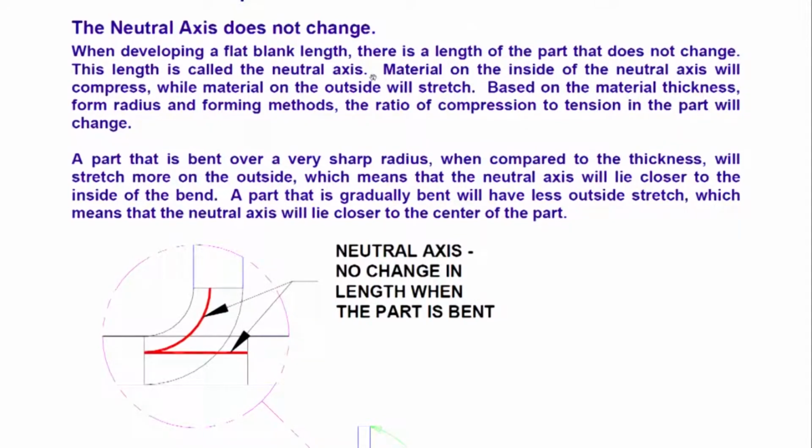You would have seen it when you bend anything in your hand, typically a small flexible material like play dough. When you bend it, you will notice that the inside gets compressed and the outside gets stretched. And you see the neutral axis is not exactly in the center. It is not a geometrical center.